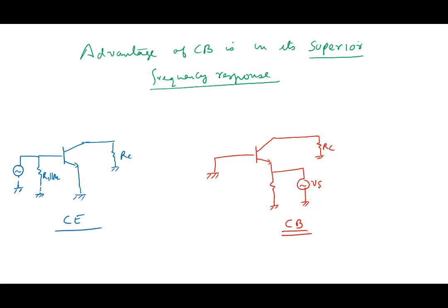Now, if you recall, frequency response depends basically on the upper cutoff frequency. So when I say frequency response, I mean upper cutoff frequency, okay? Not the lower. Lower cutoff frequencies are maybe similar. That's not the critical thing. Upper cutoff frequency, okay? So here is where you take output, RC here, okay.